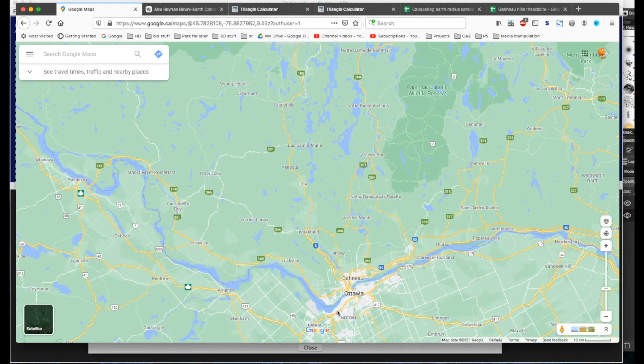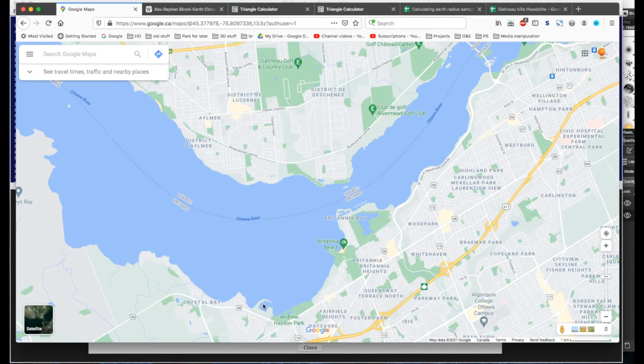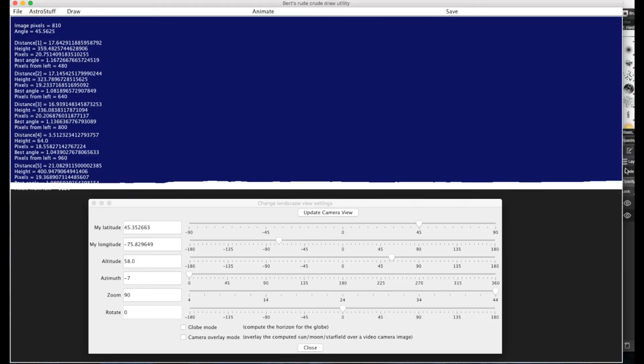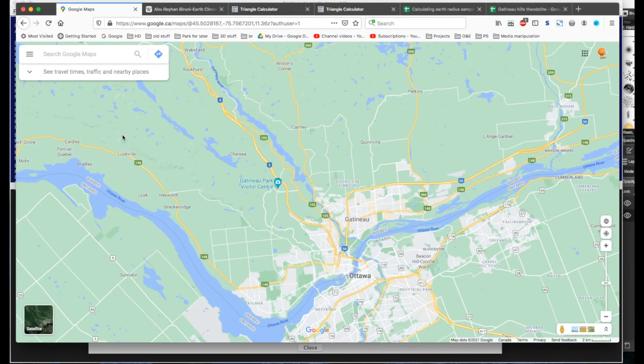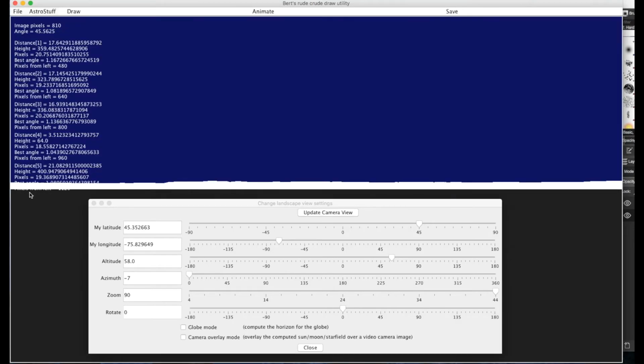And so the way I did this, I locate myself somewhere geographically. I have an azimuth and I have a horizontal field of view degree angle like this. And I know that this is so many pixels wide. I know the angle that I want, so I can calculate the azimuth in each of these directions. So I'll start at this point and I'll go off in this direction, calculating the globe Earth or the flat Earth elevation angle for each point at each step along the way. And then once I've got the highest angle up to the peak, then I can draw a line back to my horizontal.